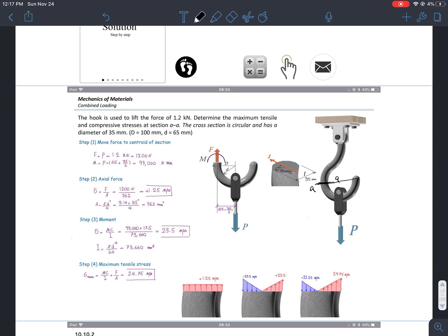So we cut right here, and this is what we have seen in the free body diagram. This is the free body, and for this free body, I have a force going downwards, P. I have a force that has to balance with this P going upwards, which is F. So immediately I know F equal to P, and once I understand that, I will look at the moment.